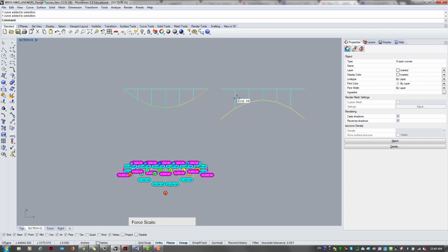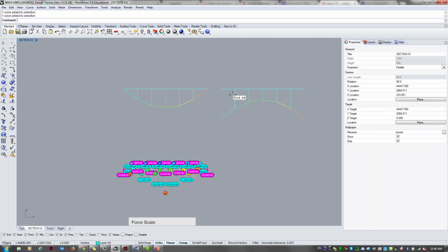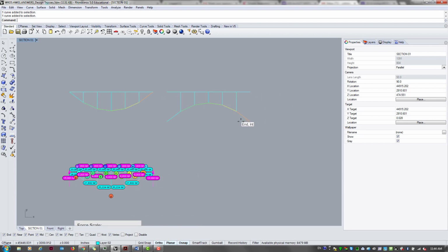So that's a compressive arch, and all the loads are basically being transferred as a point load, and therefore no diagonals needed. I'm just pointing out that if you see a combination of this flat and arch or cable shape, it's very likely that you only have these verticals in between, and the force in that flat portion is constant, and so on and so forth.